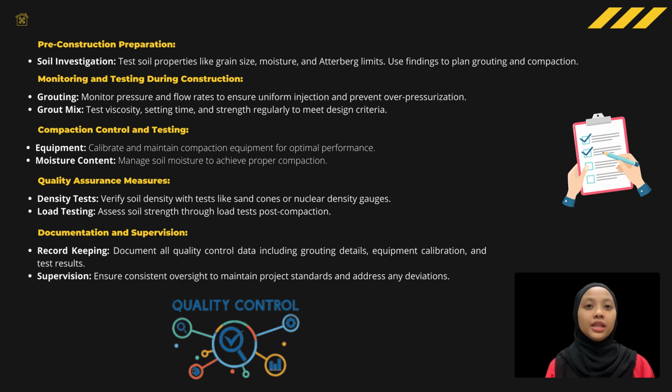After that, implement quality assurance measures by doing the density test to verify soil density with tests like sand cone or nuclear density gauge. Next is load testing, to assess soil strength through load tests post-compaction.